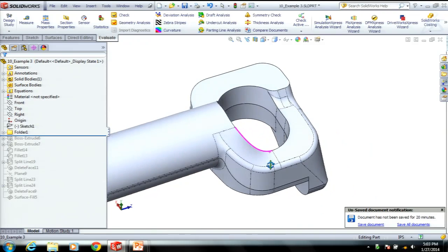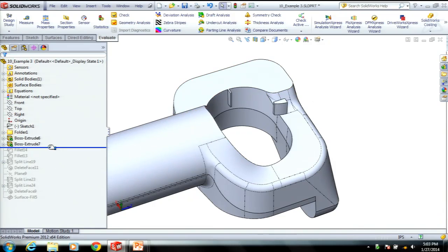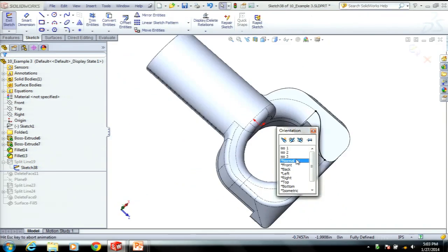So you've seen this model before, and we know we can stop fillets, so I'm going to add 2 blocks into the model to stop the fillets so I can get as much of the fillet as I want, or as I can. So by adding these blocks, I can now add most of the fillets into this area. I need to use the split line tool again to split out the top edge of my blend. Here I'm using a spline.